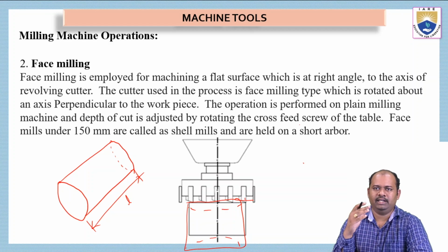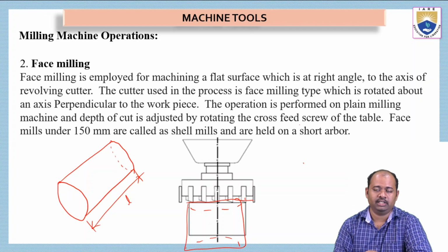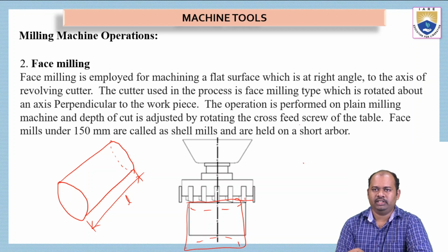It has to be aligned in this direction so that the upper part, the cross-sectional face, will be towards the top side, that is, towards the tool. Okay, where I can fix the tool in the vise and I can bring the tool near the workpiece, and the workpiece face will be milled.